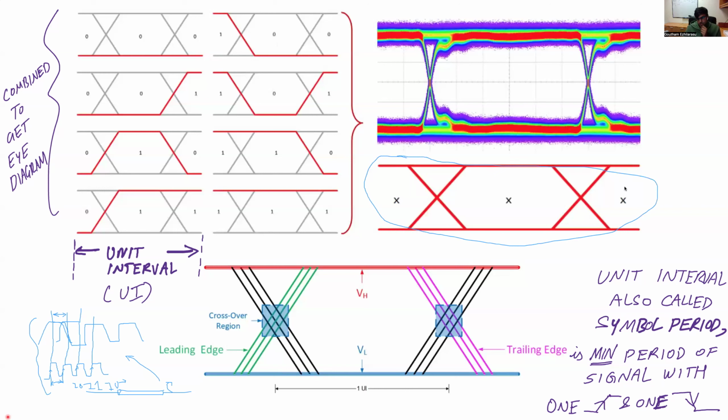And this is, of course, in a perfect case where the signals are very sharp, as was shown in this diagram. But in general, the signals are going to have distortion. So they're going to be oscillatory. They're going to occur at different times like this. And therefore, if you plot the actual eye diagram, as shown here, it's going to have a lot of variations along this direction and along this direction. For example, here it could have signals having different amplitudes. The signals can also occur at different times, and therefore the real eye diagram would look something like this.